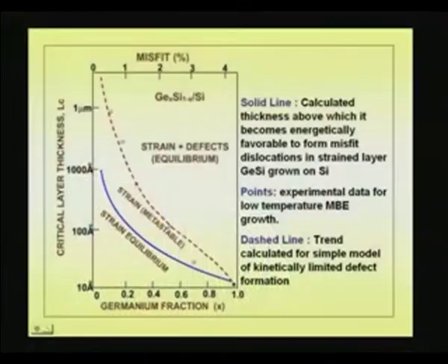That is what is shown here, the dotted line. The dotted line is actually the one which is called metastable, in the sense you grow it at lower temperature, though at this point it has a tendency to create defective layers. If you grow at lower temperatures, you can get thicker layers, not too much thick. You are not pitching for very thick layers. Base width you are talking about 0.1 microns. So, you are happy with that if you are able to get 1000 angstroms.